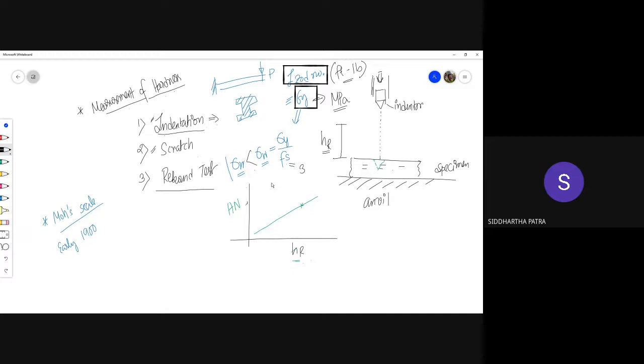Now, if you do not conduct any of these hardness tests based on indentation, the simplest test that you can do is take two materials, material A and B, make sharp objects out of those two materials, and try to make a scratch on the other using one of them. Whichever material is able to make a scratch on the other material, that material is the harder material. In this way you can rank the materials.